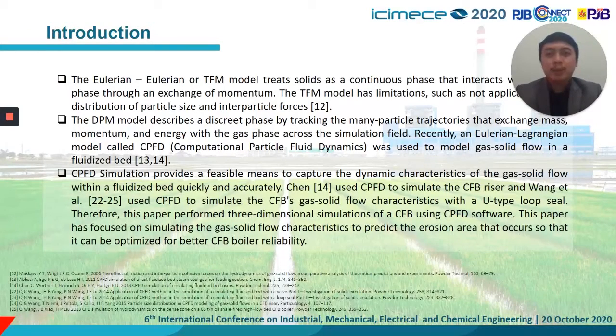Therefore, this paper performed three-dimensional simulation of a CFB using CPFD software. This paper has focused on simulating the gas-solid flow characteristic to predict the erosion area that occurs so that it can be optimized for better CFB boiler reliability.